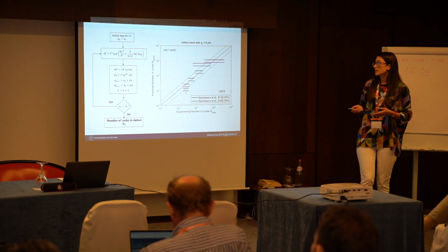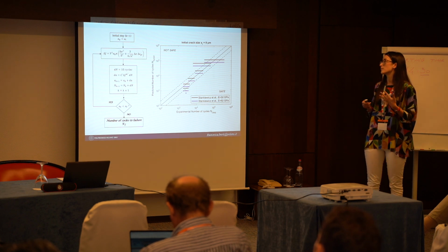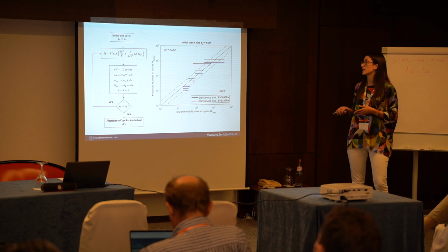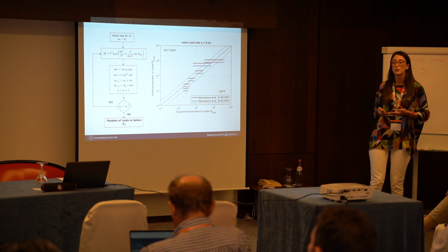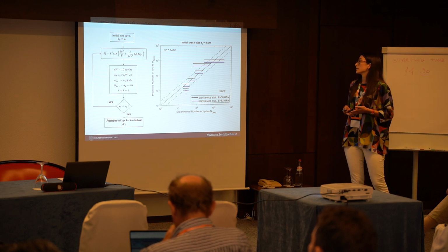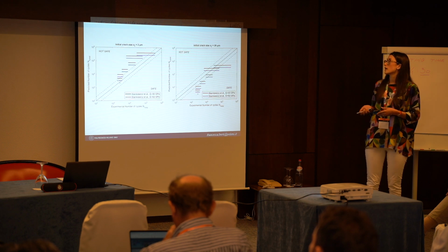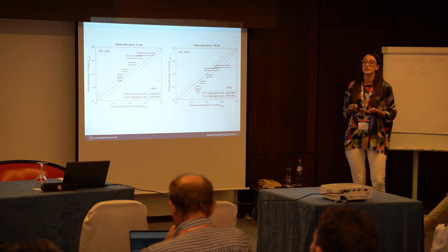And we were able to identify the C' and N' parameters for crack propagation. Then, with an iterative approach, we were able to simulate the predicted number of cycles. As you can see, I'm showing the results with an initial crack size of 8 microns, which is an average value among ours. We were pretty satisfied with these results, even if we have to say that choosing a different initial crack length can affect the prediction.